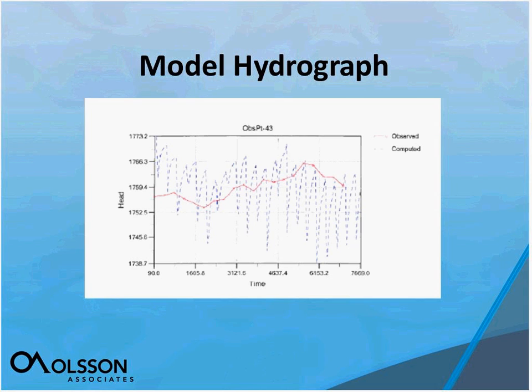But as you go back in time, you can see that the model was off for a period of time in the beginning simulations. Those are the kinds of things that we work on in calibrating the model, to try to make it match up throughout the entire period. But the important thing to note is that the model was simulating the significant drawdown during irrigation season, so that the impact of the new wells can be superimposed on the impacts of the natural conditions out there.